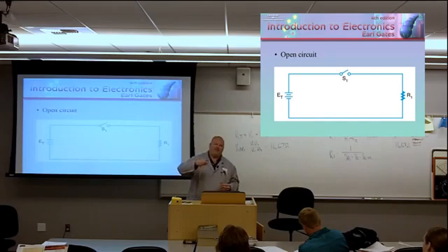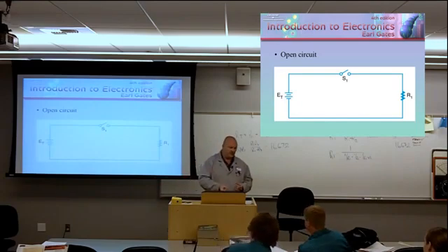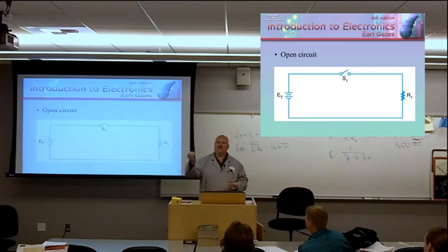Then on further probing, well, what exactly is the blender doing? Well, I plug it in, I hit the button, but nothing happens. Oh, you mean it's an open circuit, not a short circuit. Big difference. The majority of household appliances I've encountered that have failed, failed because of an open circuit condition. That's where nothing works. Now, you have to be careful because sometimes a short circuit will cause a protective device to open and render the piece of equipment dead.